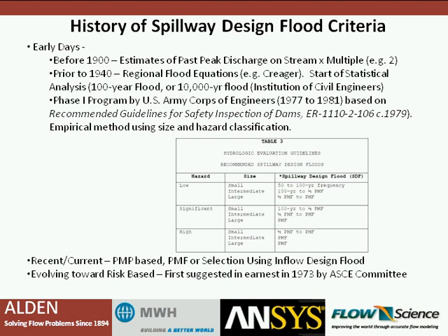More recently, we've gone to this PMF-based approach, which is based on precipitation, and this type of approach is based on a deterministic method that really calculates parameters such as the ability of the air to hold water and runoff characteristics, and that's the method that we've used more recently. And where we're headed in terms of flood selection is really towards a risk-based approach.